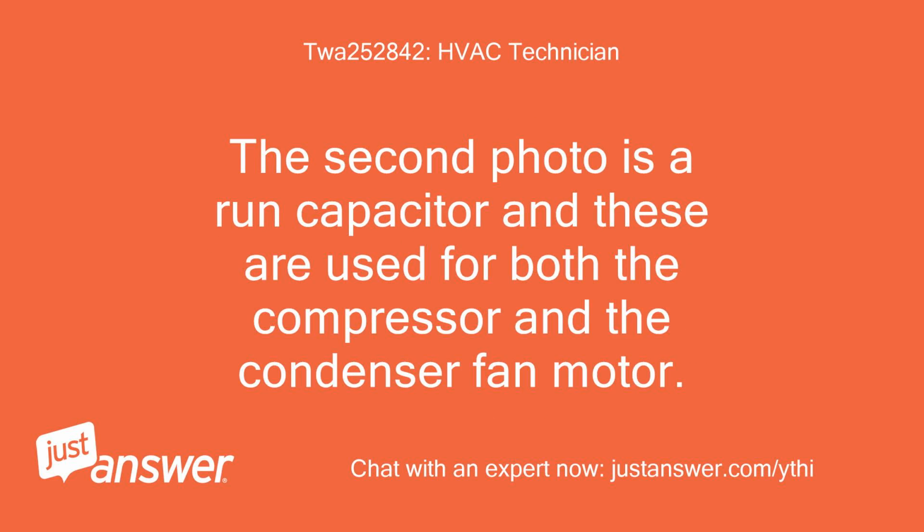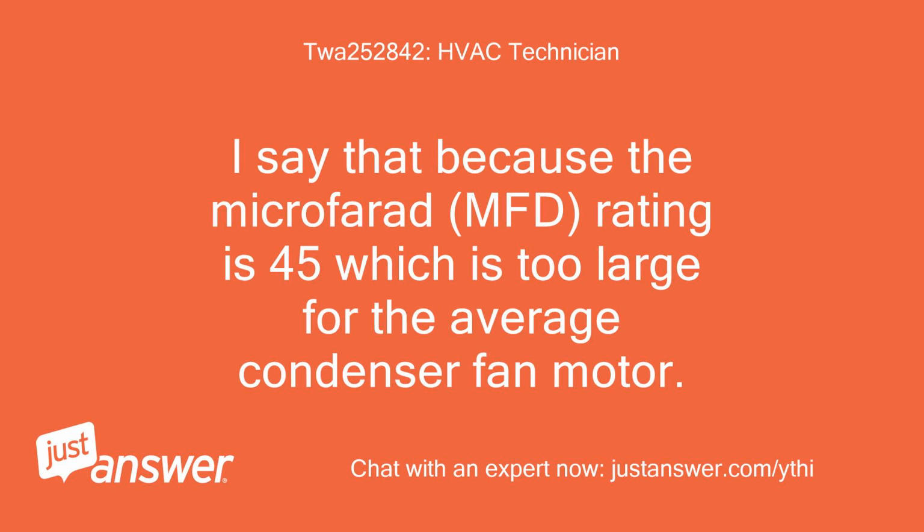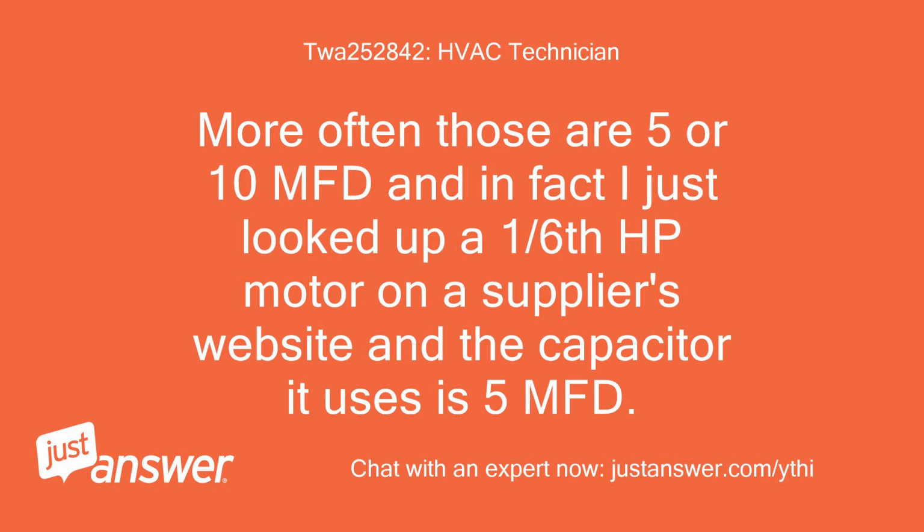The second photo is a run capacitor, and these are used for both the compressor and the condenser fan motor. Looking at the rating for the one in the photo, I can tell that this is not the one for the fan motor. I say that because the microfarad, MFD, rating is 45, which is too large for the average condenser fan motor. More often those are 5 or 10 MFD, and in fact I've just looked up a 1/6 HP motor on a supplier's website and the capacitor it uses is 5 MFD.